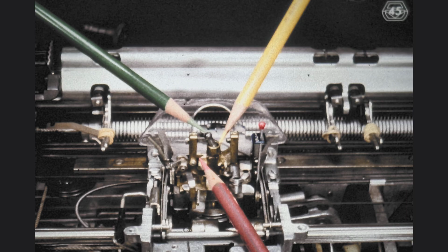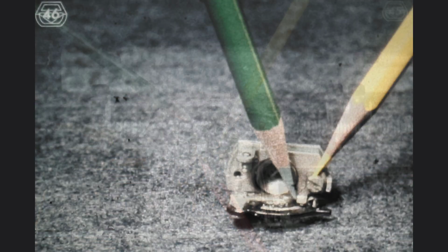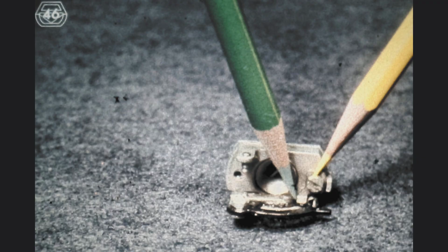Any wear noticeably greater than this requires replacement of the dog bone. This is the underside of the tilt ring. The green pencil indicates the point at which the rotate shoe restricts the lateral play of the rotate detent. Between the indicated shoe and the lock nut at the front end of the tilt ring, we must obtain 0 side play when the rotate detent is engaged with the notches in the skirt of the element.